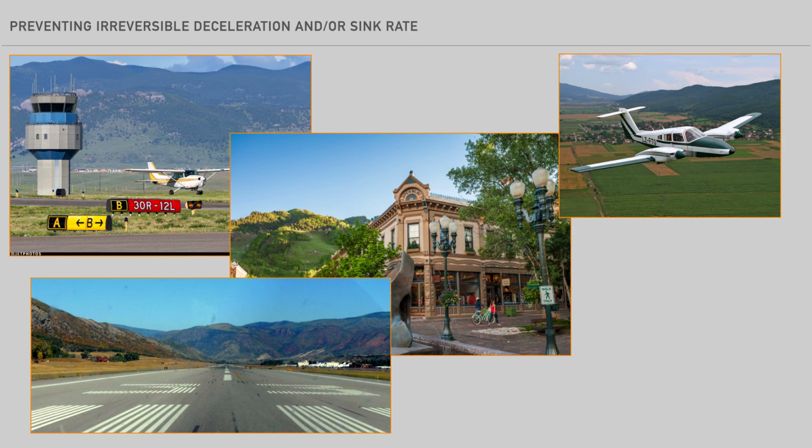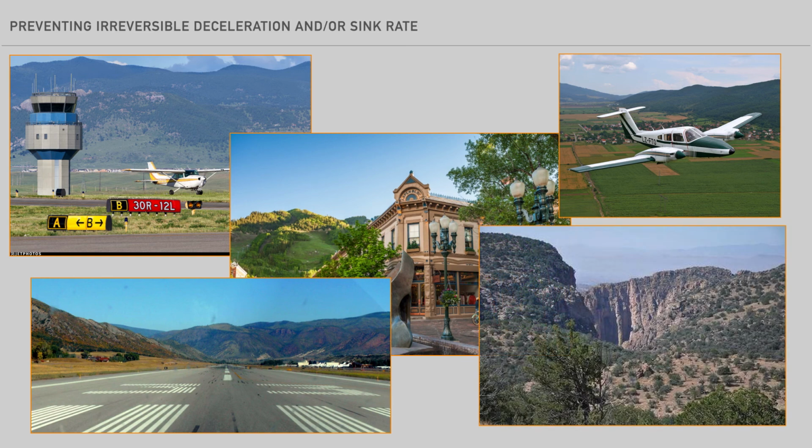The terrain is rising, and the pilot gradually pitches up and the airplane starts losing airspeed. Soon after, the airplane quits climbing and the stall horn begins to sound. The airplane has encountered an unintended deceleration and impending sink rate, which could possibly become irreversible. Let's examine more closely in terms of energy management how this happens.